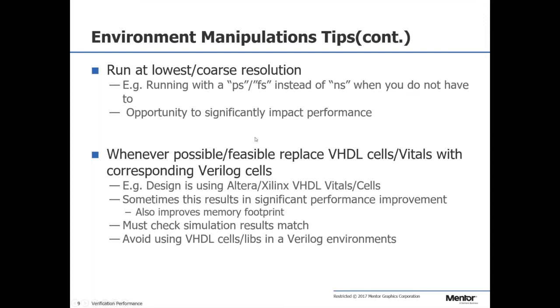Here, if you are a VHDL house and you, for whatever reason, need to do gate level timing simulations, I would highly suggest you use the Verilog gate level models. If you have a mixed language simulator, Verilog will simulate 3 or 4 times faster than VHDL VITAL models.